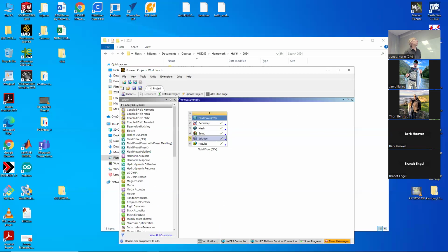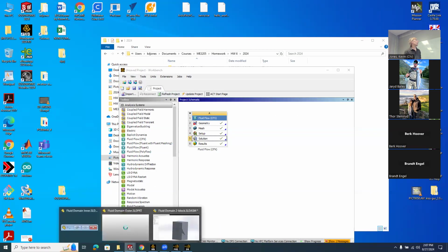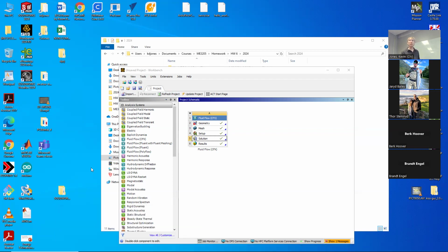So I went in, SolidWorks still up. Anyway, if you remember in SolidWorks, we started by drawing the profile, the root airfoil. And I think for this one, I set it up with a 20-degree shock angle. Use the calculator to find the body angle for Mach 8. As the Mach number goes up, the shock gets closer and closer to the body, so there's kind of a narrow gap in there.